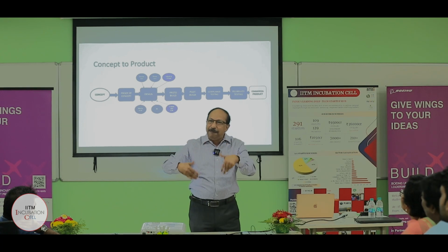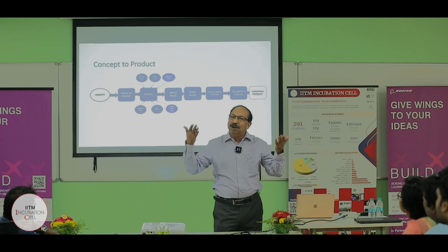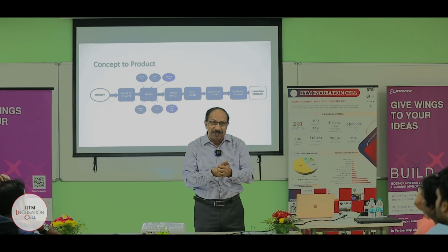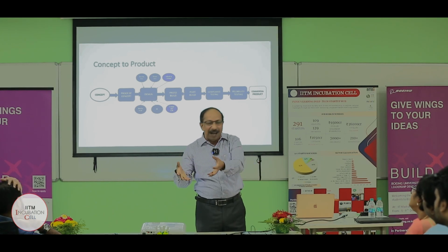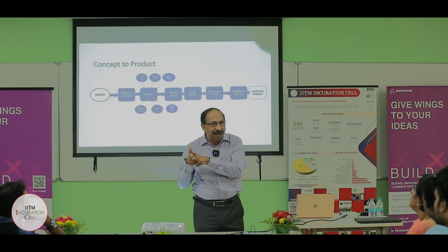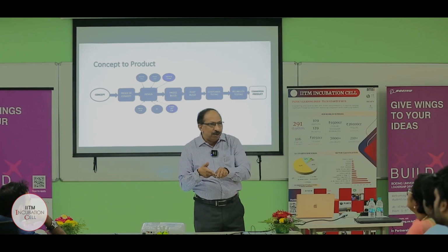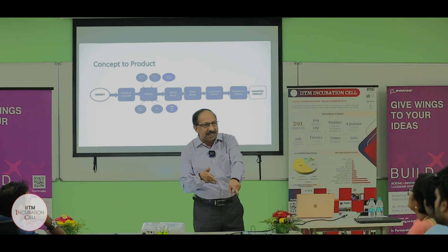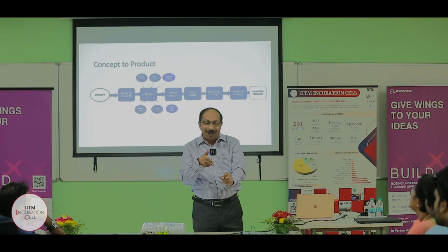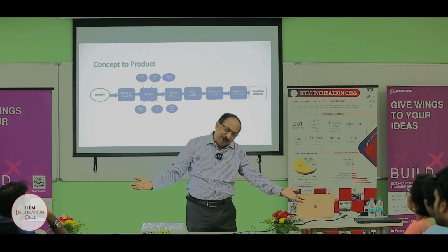So whenever you are developing hardware products, for example Boeing type of products, they will be subjected to all these tests. For example, you made a good product and you go for compliance testing, they will take a gun, the kV electrostatic gun. It will create a lightning there, like through air. A spark goes into your open spaces, wherever connectors or openings are there. 11 kV and all. You can see that spark going in, and your product dies.